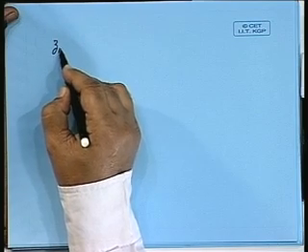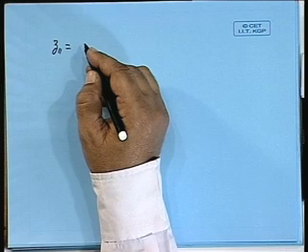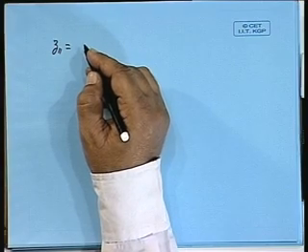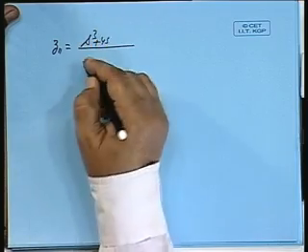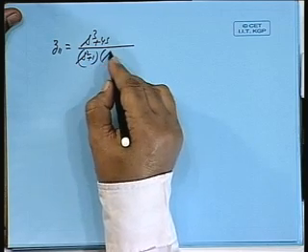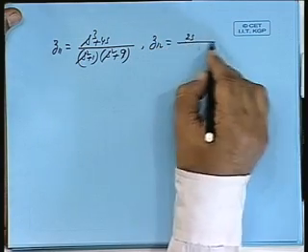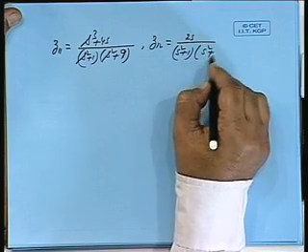Now, there are different types of specifications for two port networks. So, let us synthesize by this method for different specifications. Suppose you are given Z11, let us take an example, Z11 having LC elements, s cubed plus 4s divided by s squared plus 1 into s squared plus 9, and Z12 is equal to 2s by s squared plus 1 into s squared plus 9.